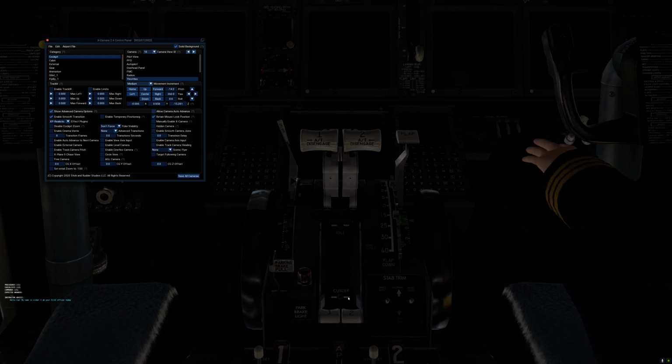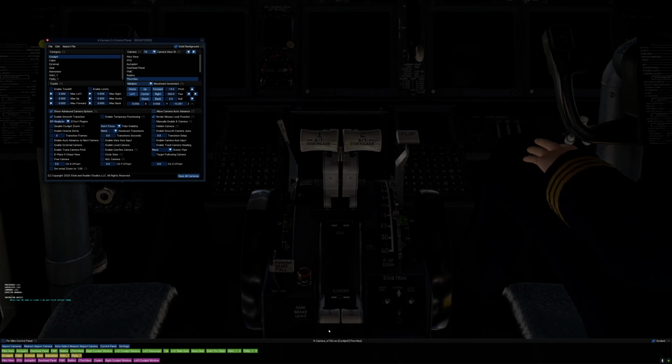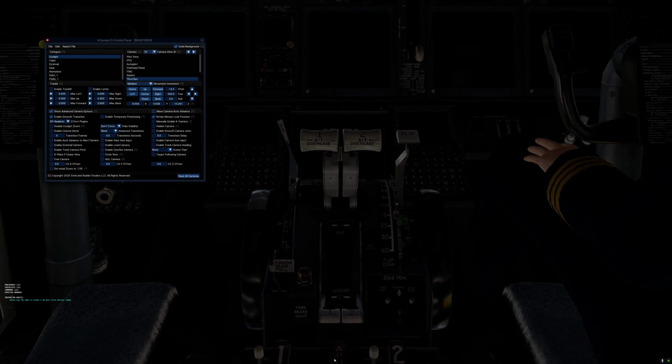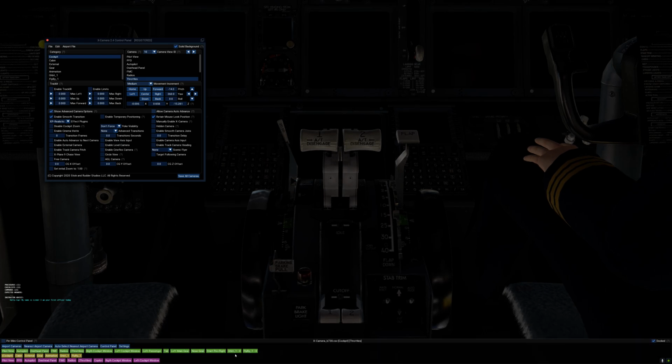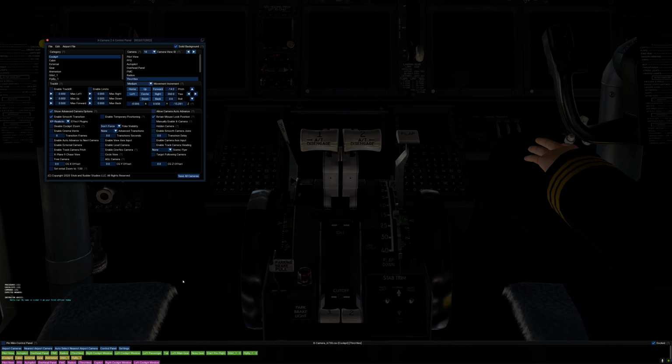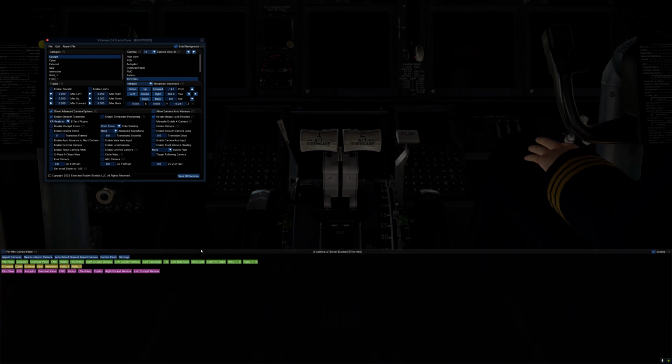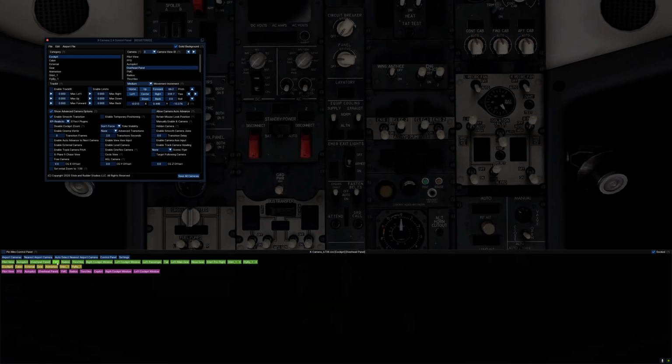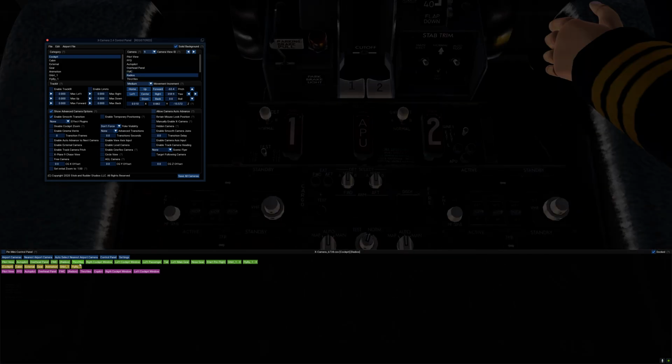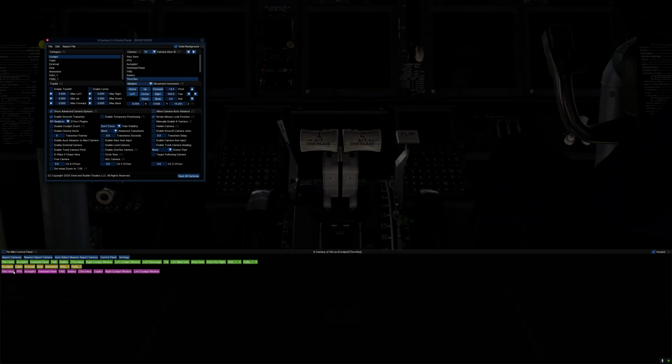But also notice how I leave a 4-inch gap, or in my case 4 inches, yours probably may not be quite as big, but leave a little bit of a gap, because if your mouse drops to the lower part of the screen, you're going to get what's called the mini control panel. And the mini control panel shows all of your available cameras. These are cameras that have an assigned view, and there might be times that you want to use this mini control panel to go to various cameras without having to use the Orbweaver.